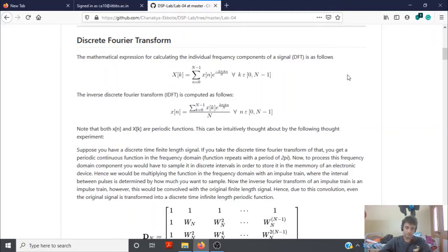and before that. So if you really want to work with such frequencies in a computer, you need to discretize it, right? You have to sample certain frequencies from the frequency spectra in order to store those particular frequencies and be able to work with them using a digital device such as a computer. So what a discrete Fourier transform does is it just discretizes the continuous frequency spectra which is obtained from the Fourier transform of a finite length discrete sequence.